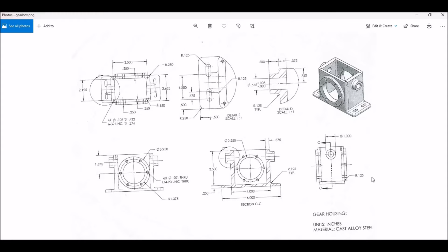Because they can do things that SketchUp just can't do at the moment. For example, it may be easier to sketch in SketchUp, but in SolidWorks you can do things such as finding stresses and evaluating for strengths and weaknesses, and mass evaluation such as the center of gravity of a part and the mass moments of inertia of a complicated part. It does all the math for you, and SketchUp doesn't have any of that. SketchUp's great for illustration and visual purposes, especially for architecture.